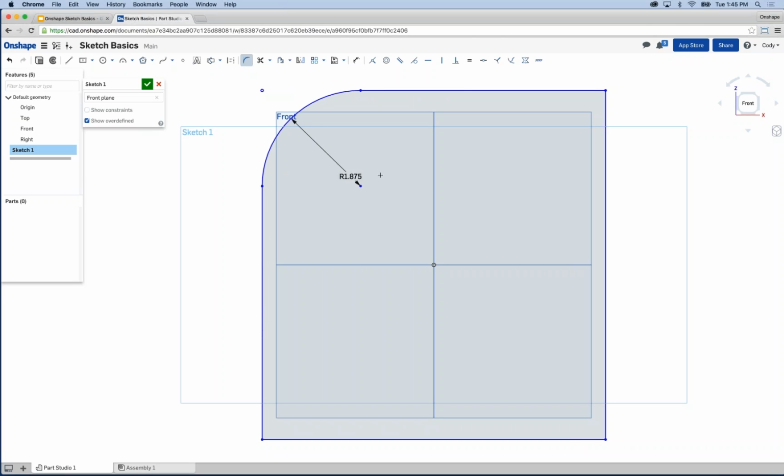It's useful if you're trying to eyeball the size of the radius, or you're trying to get it to maybe match other geometry close to it. You don't have to left click a point and enter a value. You can left click drag. Of course, you still need to enter a value, but it allows you to dynamically resize the fillet and kind of get it close to the size you're looking for before you actually create it.